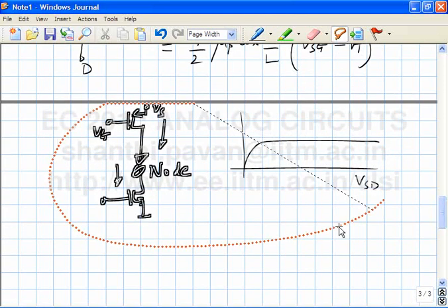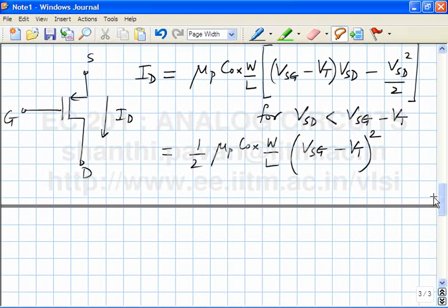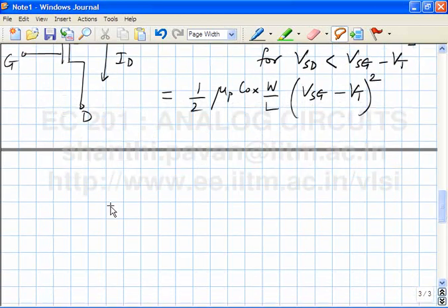sufficiently large. And in modern technologies, it's possible to have both NMOS transistors and PMOS transistors built on the same IC. Such technologies, where you have NMOS and PMOS transistors on the same chip, are called CMOS, where C stands for complementary and MOS is metal oxide semiconductor. NMOS and PMOS are a complementary set because the PMOS can do stuff which the NMOS cannot and vice versa. As you will see, going further in this course, it's very convenient to have the complementary device, and it opens up a whole bunch of nice new circuit possibilities, especially when you start putting NMOS transistors together with PMOS transistors.